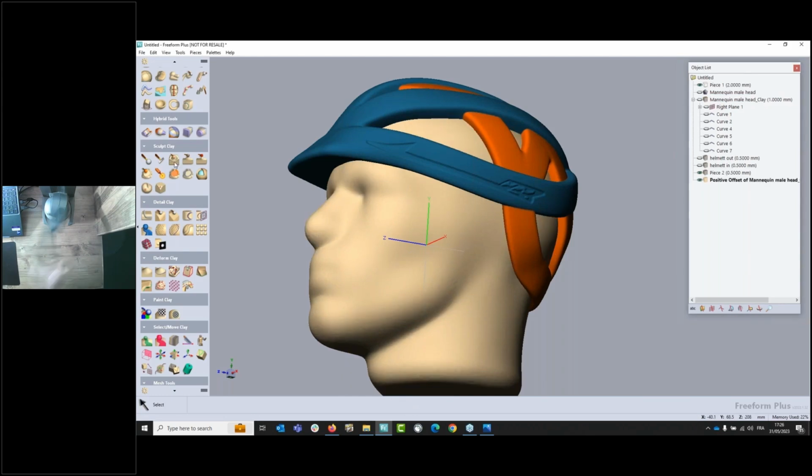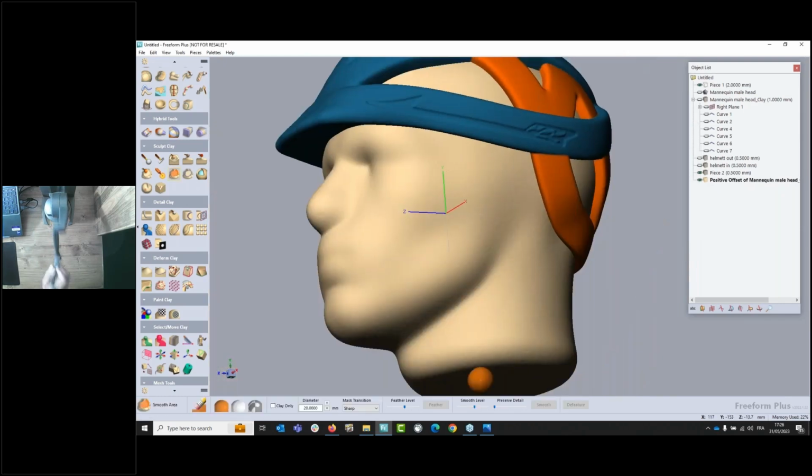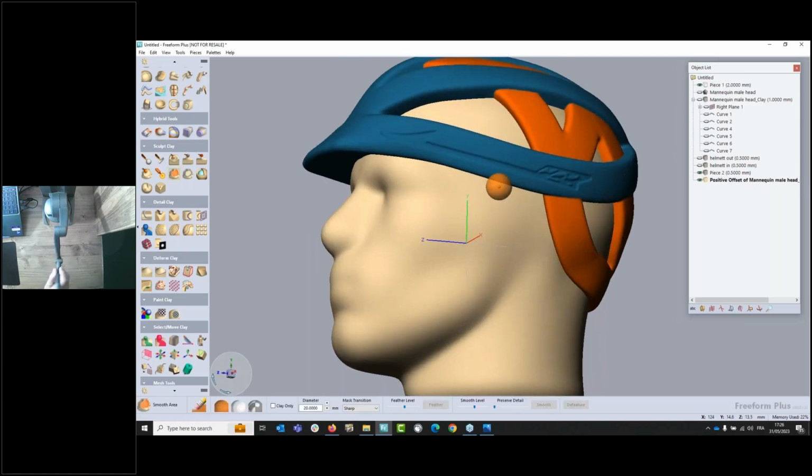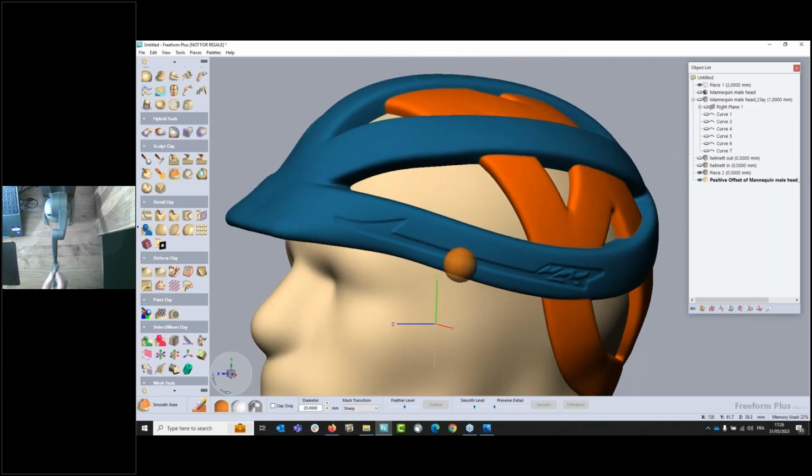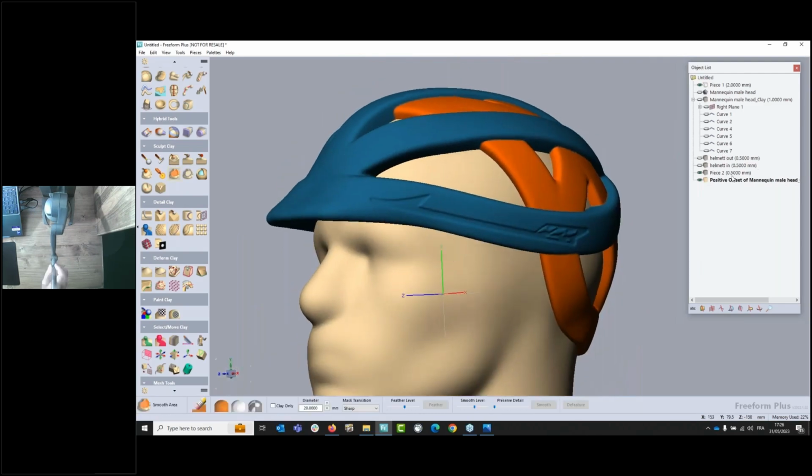Here it is. Let me smooth the object to remove the small grain size. Select everything, smooth. The smoothing tool is not sandpaper. It's really an average, which means it will not change the size of my object. And now I need to remove everything which is not in front of my helmet. Let me first rename this one. This will be the foam. It's always better to give pieces names. And this will be my helmet final.